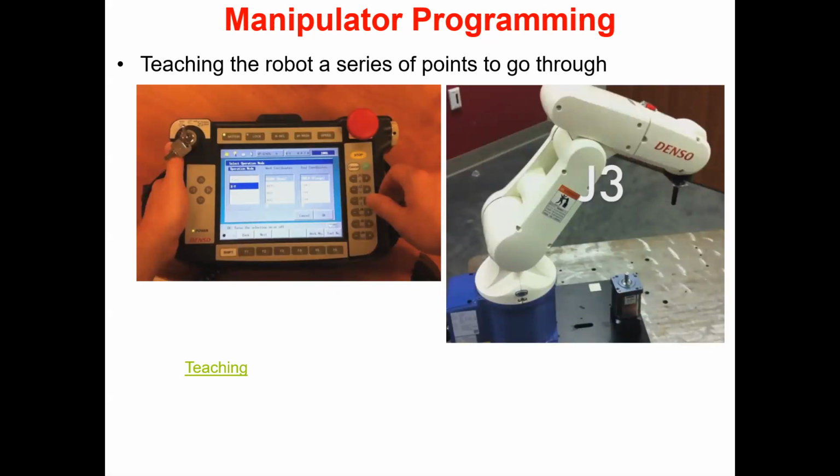Okay, so trajectory planning is another area in manipulators. You use not only the piecewise linear curves, but spline, parabolic curves, trapezoidal velocity profiles. You can bring them in and plan a very smooth trajectory. Okay, so these are built into the system. When you specify 0, 1, 2, 3, 4, everything is happening internally. You don't have to worry, right? And the sample trajectory that is being generated would be very smooth.